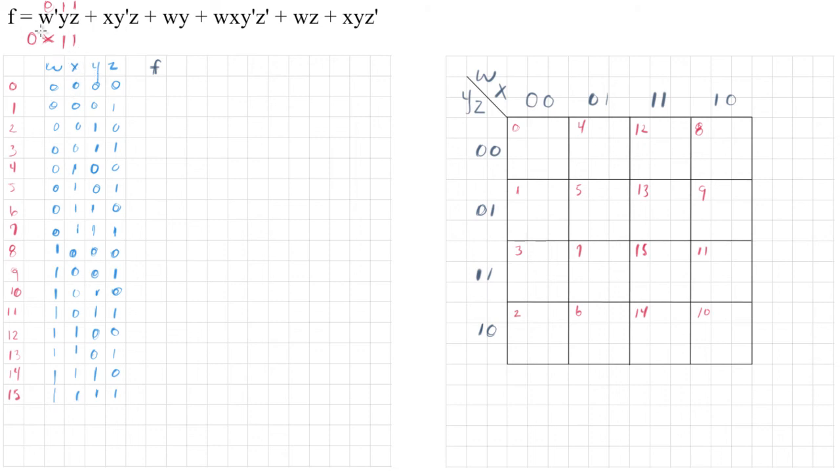Now if we look down this truth table to all of the possibilities that start with 0 and end with 1, 1, we're going to notice that there's going to be 2 of them. So we're going to put a 1 here for each of those 2. So let's do that. I got a different color for that. So starting with 0 and ending with 1, 1. But we don't care about what X is. So we have this one here, 0, 0, 1, 1.